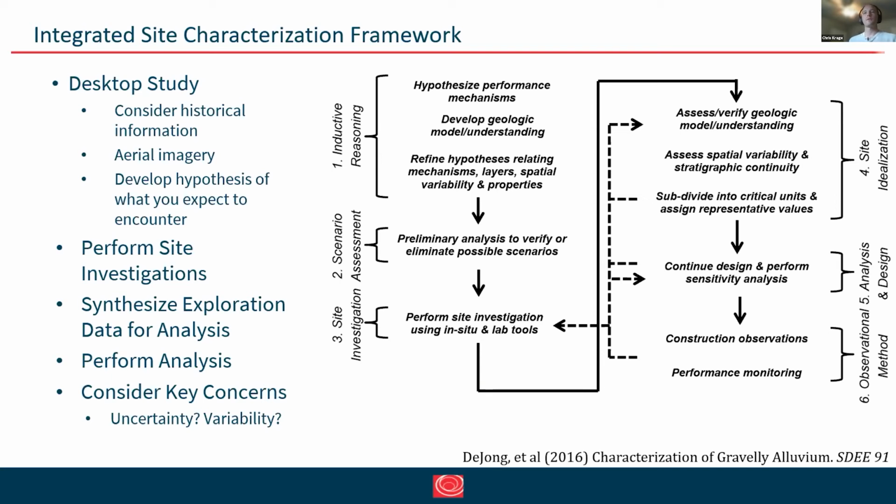Or it could be in support of a phased effort, where CPTs or some other high production rate technique can be used in advance of some more targeted or specific lab test or vane shear test operations, as was performed in this study. And then, of course, this all affects the analysis and design. If you have just a limited data set, there's going to be some larger uncertainty, and that will come forth in the analysis and design phase. And that may necessitate returning to the field and doing some more explorations and repeating this process.